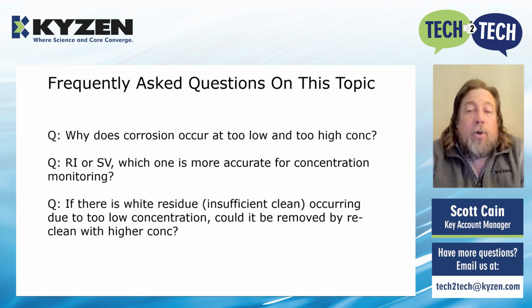If there is white residue caused by insufficient cleaning, occurring due to low concentration, could it be removed by recleaning with a higher concentration? Historically, yes. White residue is a cosmetic error that will happen on the boards. It's not something that historically will cause problems. But if you get that concentration back in line and run it again relatively quickly, then you will be able to remove that white residue. So you're providing a product that meets the integrity that your customers expect from you.